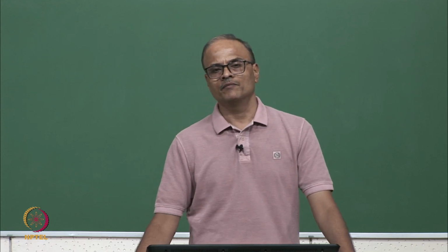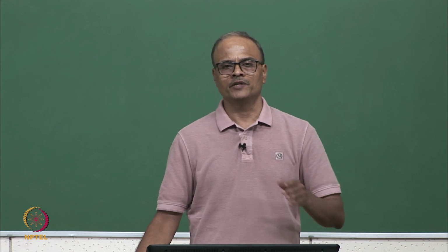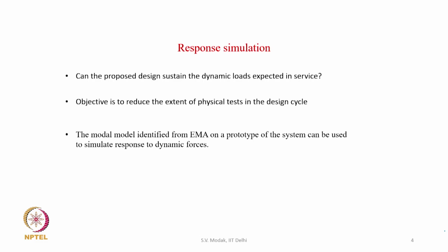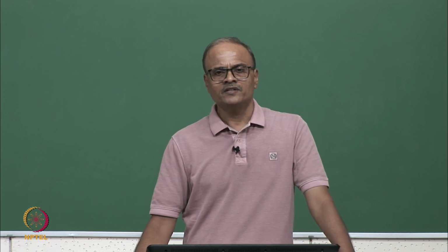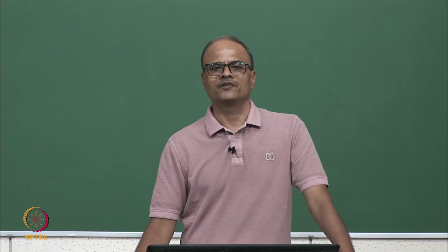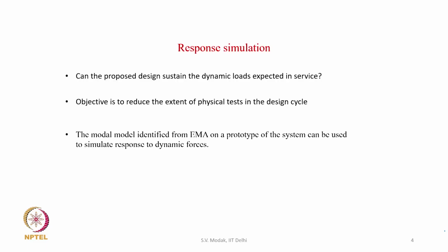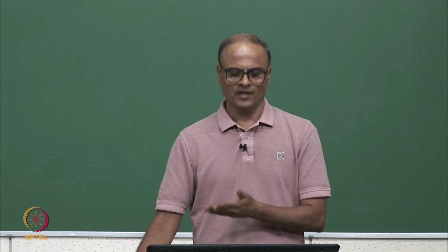In this context, the experimental model identified from EMA can be used for response simulation. We need to have one prototype of the product based on the proposed design, so that the modal test can be conducted and the model can be identified. This model can then be used for predicting the response of this product to any forces which are likely to be experienced by it in its service. Also, we will later see that if there are some small design modifications we want to make, then the effect of those modifications on the dynamic characteristics can also be evaluated using the experimental model. That application we will study later.